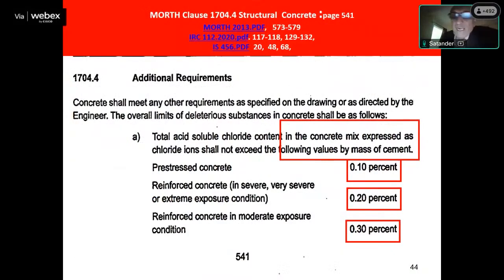Now coming to the other points with regard to quality control, I will quickly go. Just please refer to the MoRTH section. How to find chloride content, what is the chloride content limit in the total. Suppose you are working in Rajasthan or Gujarat. There the aggregate is mostly black or reddish in color. They have chloride. So you reduce that quantity, add sand, or you can change that proportion. Suppose your quarry has high chloride content, so use the minimum, use other material also. In this way, you have to adjust: 0.1% for prestressed concrete by weight of the mix, and 0.3% for reinforced concrete.